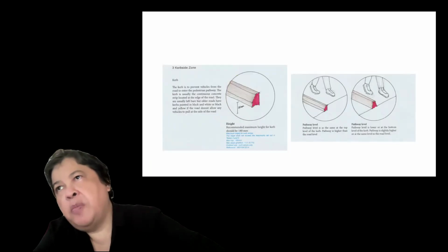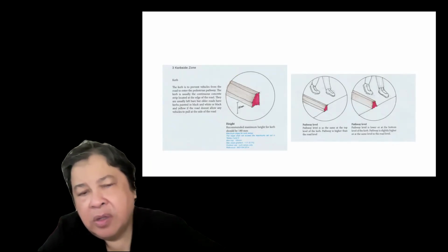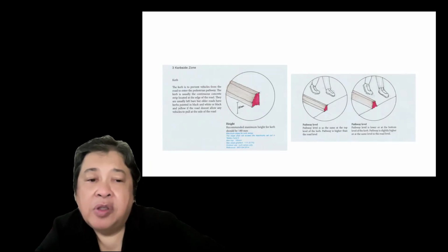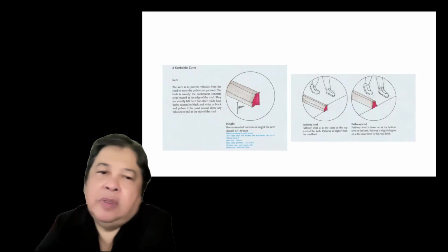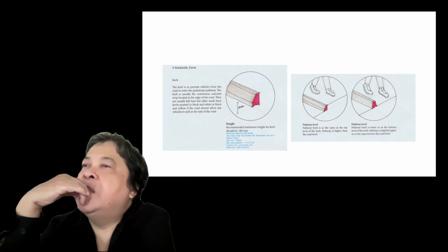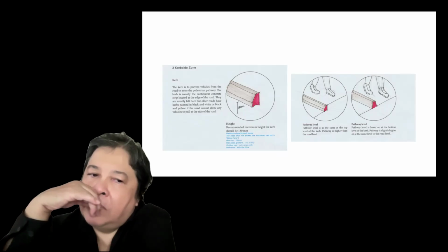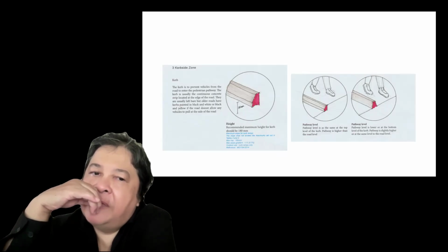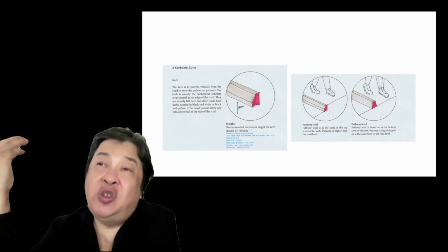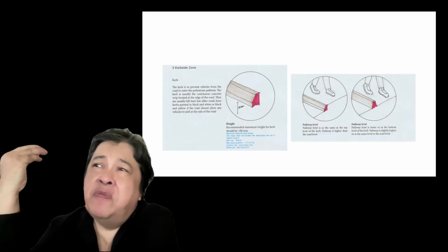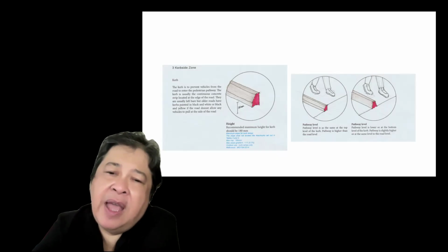In Singapore, the curb height is about 165 to 170 millimeters. Sorry, not centimeters, I'm going to talk about millimeters now. So we recommend 180 millimeters. If I made a mistake with the meters, millimeters, or centimeters, please excuse me. So from 165 to 170 in Singapore, in Malaysia we need to go to 180, rather than the proposed, or what many in the built environment already have, 225 millimeters, which makes it very difficult to create ramps at the junction.